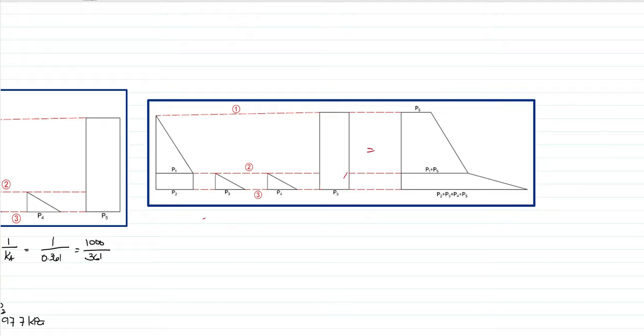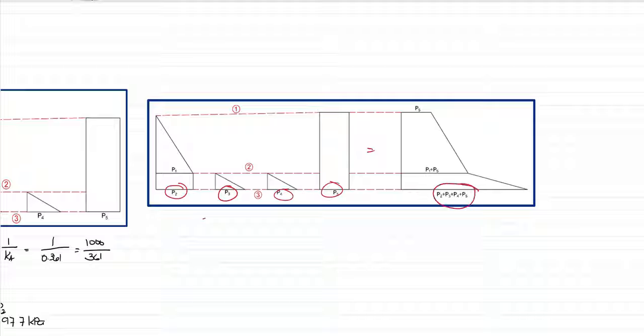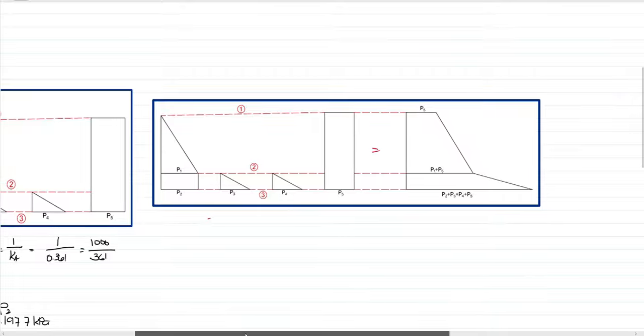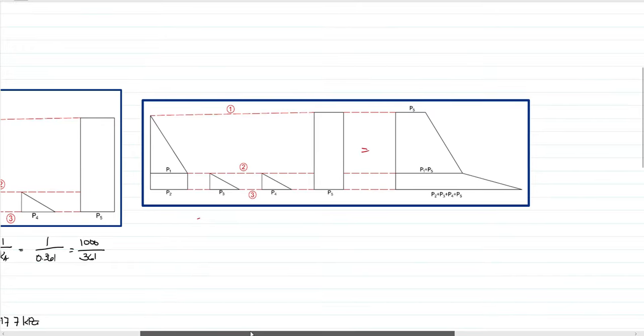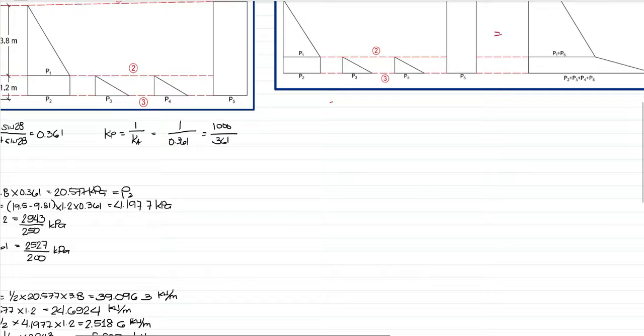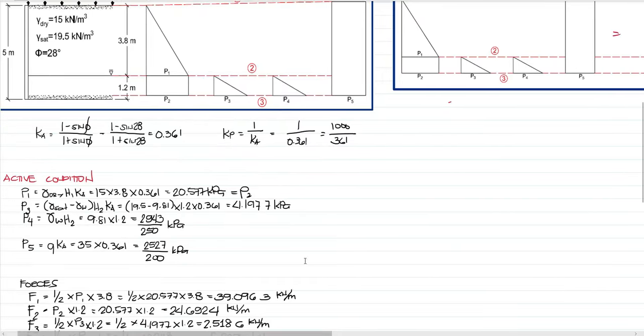Then, we go to the lowest part of the second level diagram. So, P2 plus P3 plus P4 plus P5. So, here it is. Now, as you can see, we have pressures per level. So, we can form two trapezoids, and using the area of these two trapezoids, we can get the active force. So, the forces should be equal to the answer we got earlier using the force method. So, using the pressure, we could have the one at the top, P5, which is automatically equivalent to